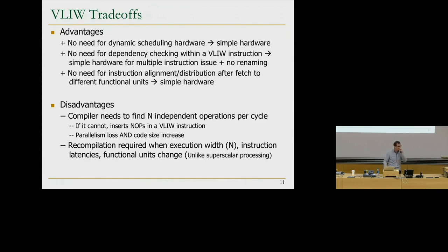Would no operations actually be some instructions like a branch that never does anything? Exactly. It's basically an operation that doesn't do anything. It doesn't change anything, but it just takes that cycle so that no other instruction can go in that cycle. For example, branch not equal that looks at the same register twice. That's right, yes, exactly. You can repurpose some other operations as no operations, as long as you don't have any side effects, you don't change anything in the state.